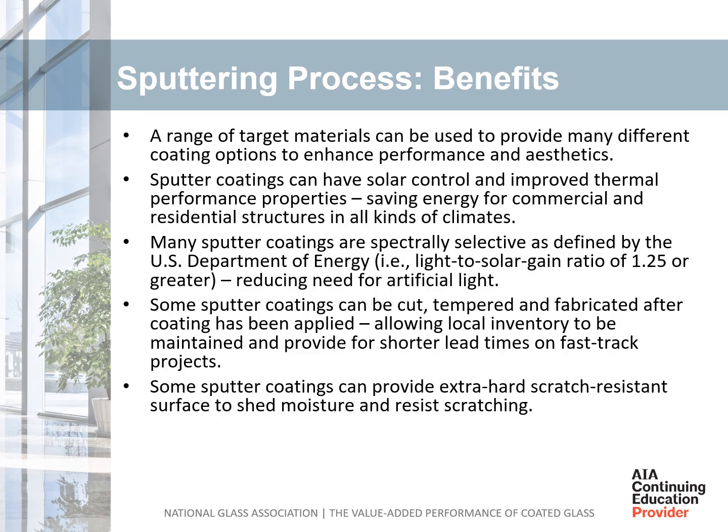There are benefits associated with using the sputtered coating approach. The key difference being the ability to engineer coatings layer by layer, each layer having a specific purpose. This opens up a range of options to the coating engineer in order to enhance or suppress a given characteristic. The high-performance sputter coatings can provide optimized solar control or low-E properties, which maximize saving opportunities. They are spectrally selective in order to allow for daylighting applications. There are a range of products that can be cut, edge-seamed, and tempered from stock sheets.